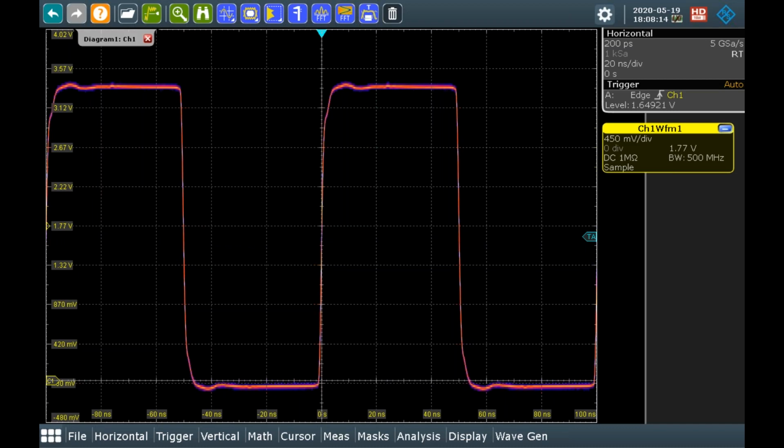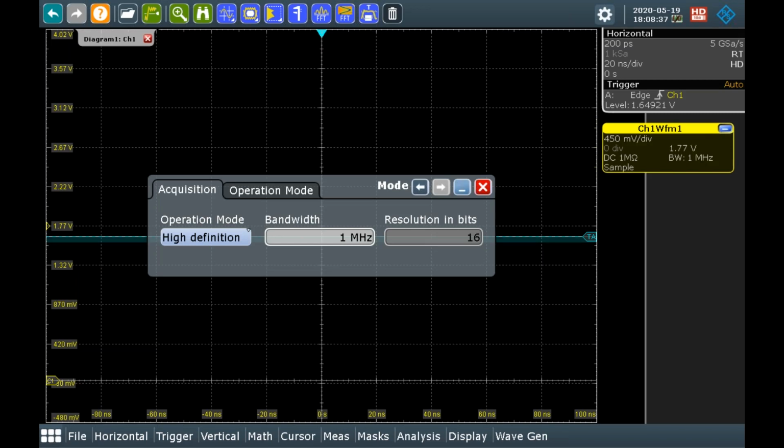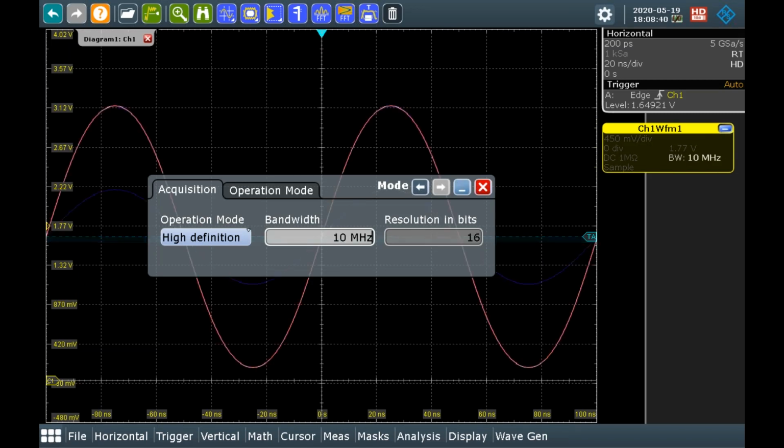Okay, we'll go ahead and do this demonstration real quick, and then we'll jump back over. So right here, I have a fairly simple 10 megahertz clock. I've got a small demo board in front of me. So what we're going to do is take a look at what happens when we limit the bandwidth. So 10 megahertz is a nice round number. So if we limit our bandwidth down to, say, 5 megahertz, let's see what happens to our signal.